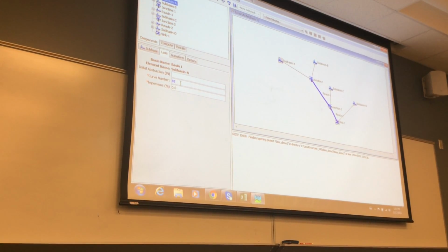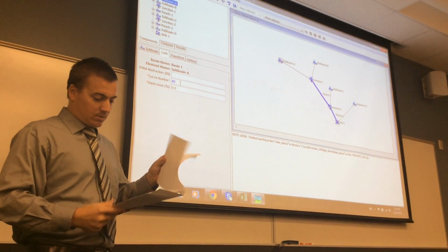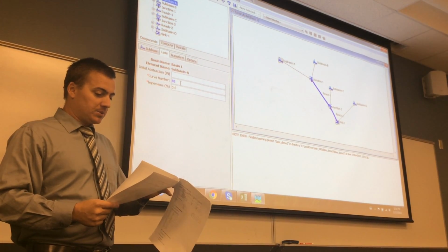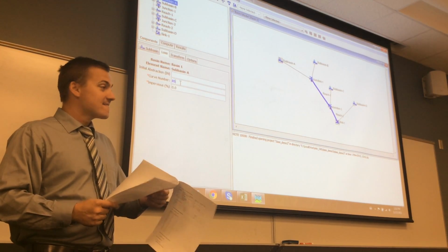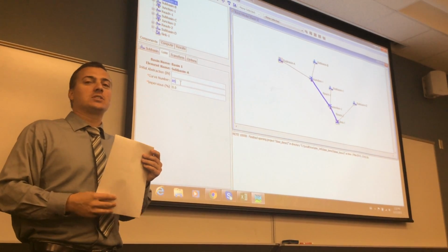There's a table here for the curve numbers. So do you want us to be on the conservative side? So with this one, you'd have to take like an average of it? Fully developed urban areas, soil type C. So when you go there, you have some choices here. Conservative, usually, it's your choice.